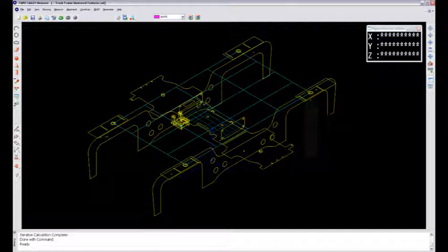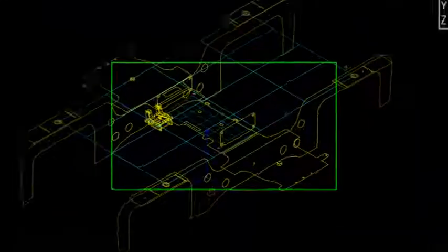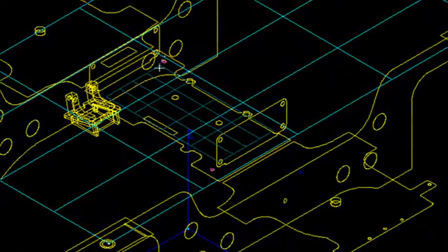My B's, here's B2 and B3, B1 and B4, all of those things now are best fitting into that location. Now, here's my hole and here's my slot. And again, when I do the iterative and I don't set weights, it's going to best fit as best as it can all of those points.